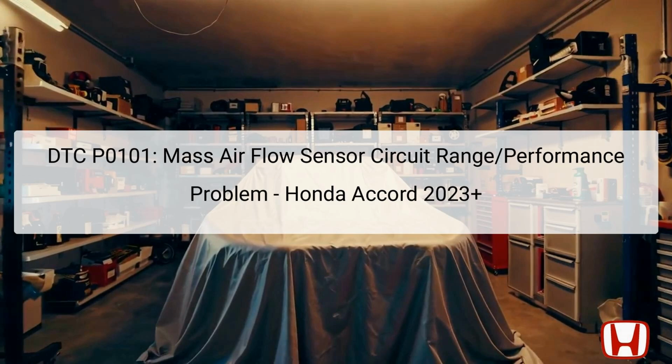The exact location of the MAF sensor is typically after the air cleaner, positioned in the intake air duct. If the MAF sensor fails to operate correctly, it triggers this diagnostic trouble code, leading the technician to investigate the cause of the output frequency deviation.